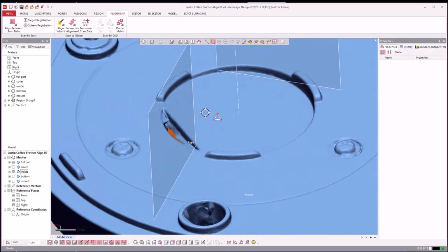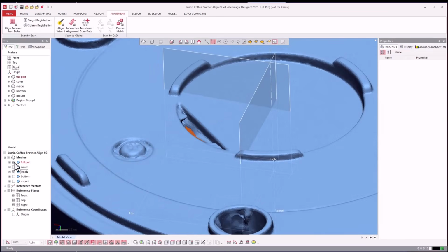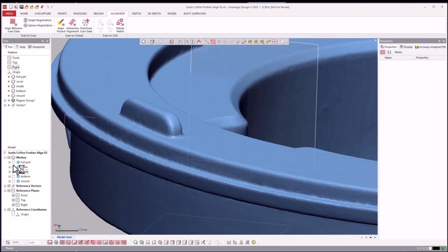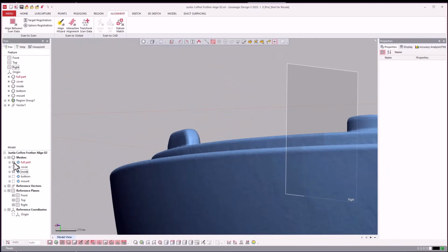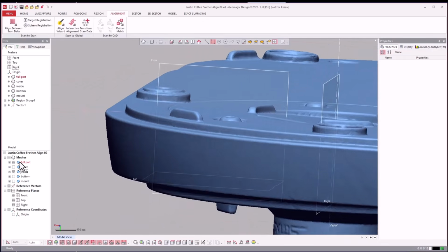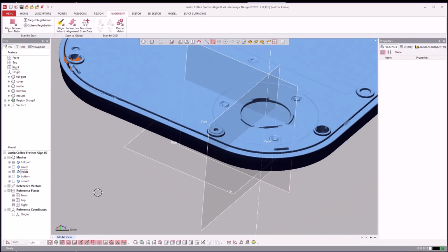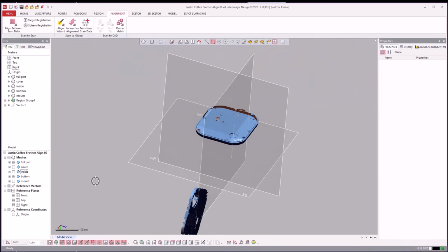So just like before, if I hide my main piece, you can see the overlapping areas. And if you slice the section through, we'll double check all of the alignments afterwards too. So I'll go ahead and turn that off, turn on the bottom, hit save usually before I move on to the next one.